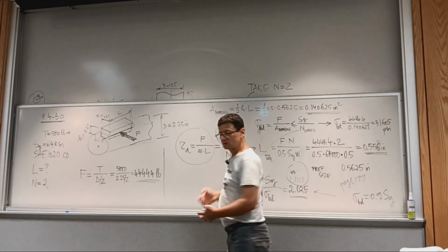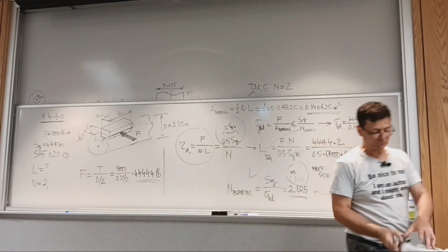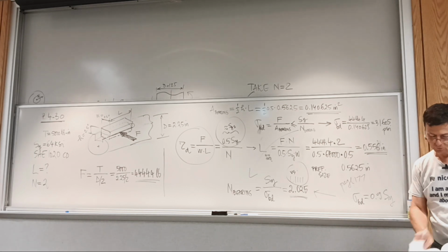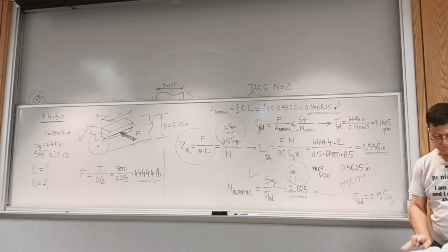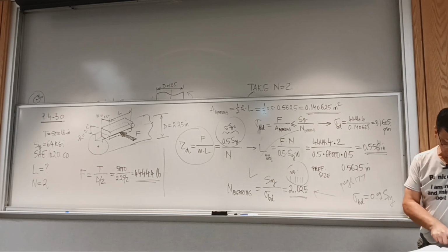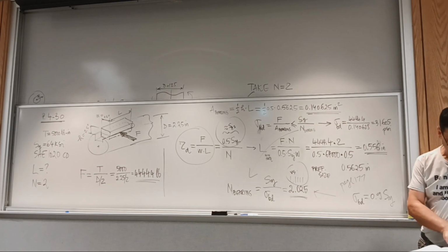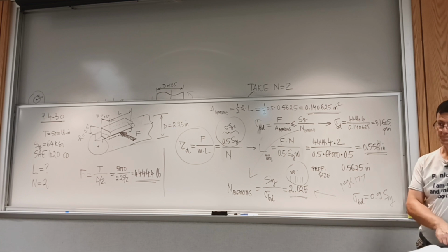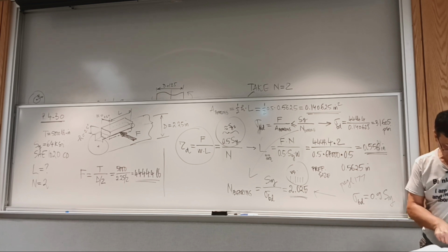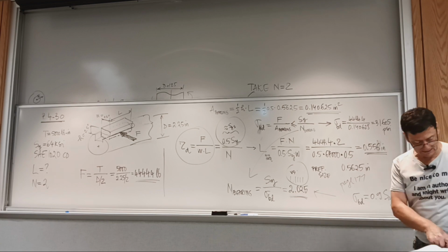So we went to where all the recommendations about design factors are, the back of the book. We can go to the chapter, yes, but this is all together, and it's where the properties end. So I'm on page 790, probably where you got lost. We have design shear stress for direct shear and for torsion shear stress. Can you see it on page 790? And you have static loading. Yeah, that was assumed.